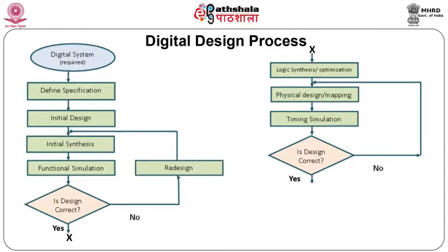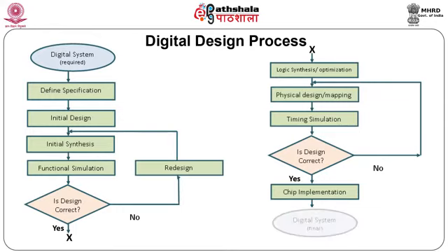During the redesign process, optimized placement of the logic components and routing is reworked. Once the timing characteristics are obtained as per the design, then the design is finally implemented into the chip. Thus, we get the design of desired digital system.